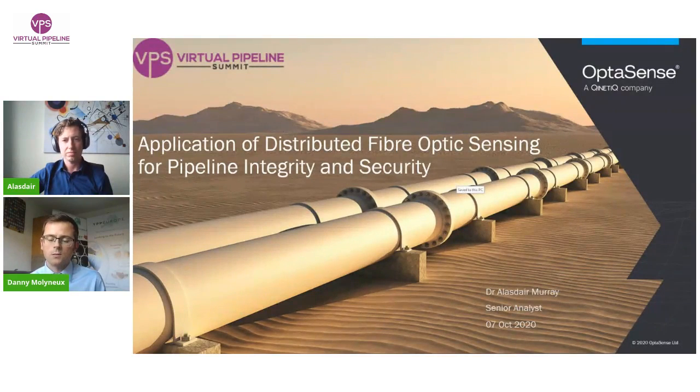Veronica Iglesias asks, what type of fibre optic cable do you use for this project? So our systems generally rely on a standard single mode fibre optic cable. Multi-mode causes problems, but there is work going on to look at using specialist fibres to allow detection at greater ranges, or to enhance the sensitivity of the system. But typically it can be installed on any single mode telecoms fibre.